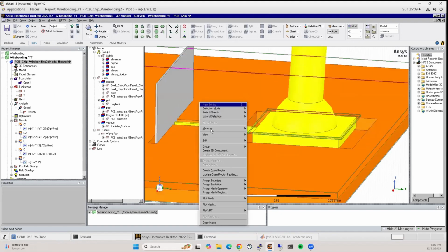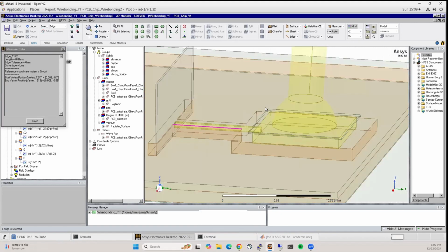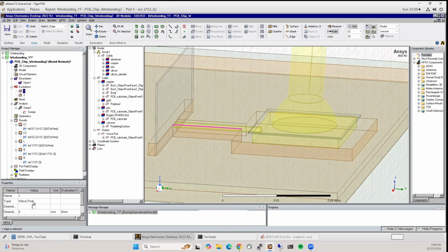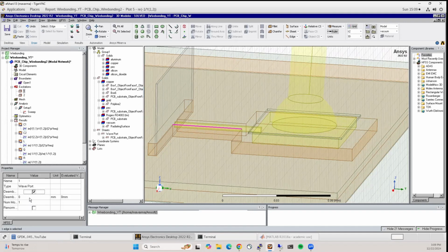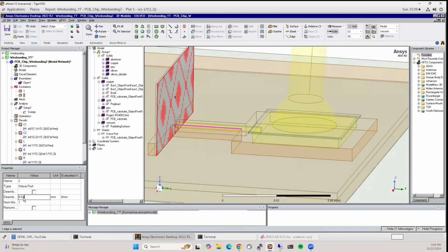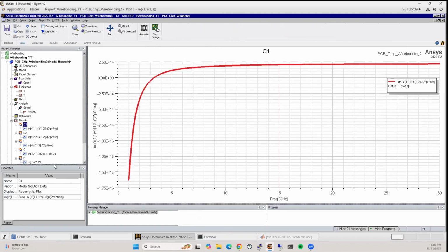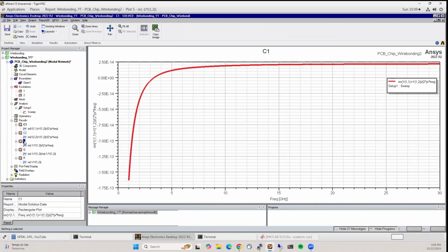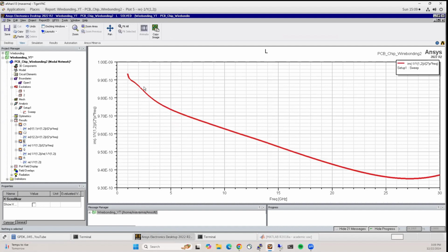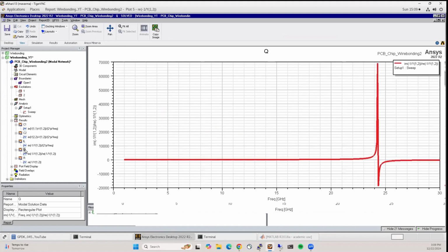And then on this side, it is measured edge 0.04, right? So port 1 needs to be de-embedded by about 0.69 millimeters. Port 2 by 0.04 millimeters. Okay, and that'll obviously change the S parameter, Y parameters, and you can see now that L has changed. And this is sort of much more stable if you look at the value, right? It's close to 0.96 nanohenry, right?